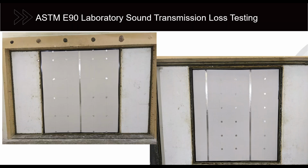Now you see the perimeter of the wall. We always seal that with mastic. Obviously you wouldn't do that in the field, but you do want to make sure you get an airtight seal around the perimeter in your field condition as well. In the lab, almost all tests are run with foil tape and acoustical sealant, sealing the joints. And this was proven in a paper by the National Research Council of Canada to perform the same as a level 3 joint compound treatment, which is good news for the labs, because if we had to do a level 3 joint compound, it would take multiple days to do a single test, versus with this method, we can run multiple tests in a single day. And there's no difference in the STC rating.